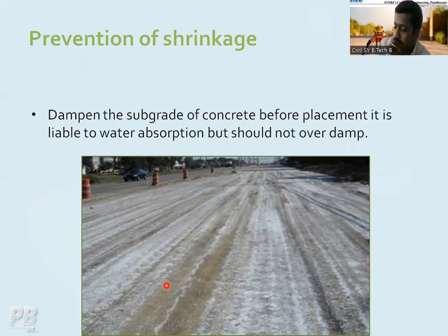At the bottom during your construction. Okay, why are we using this damp proof course? To avoid the entry of water from the capillary pores. That is from the bottom, correct, DPC.